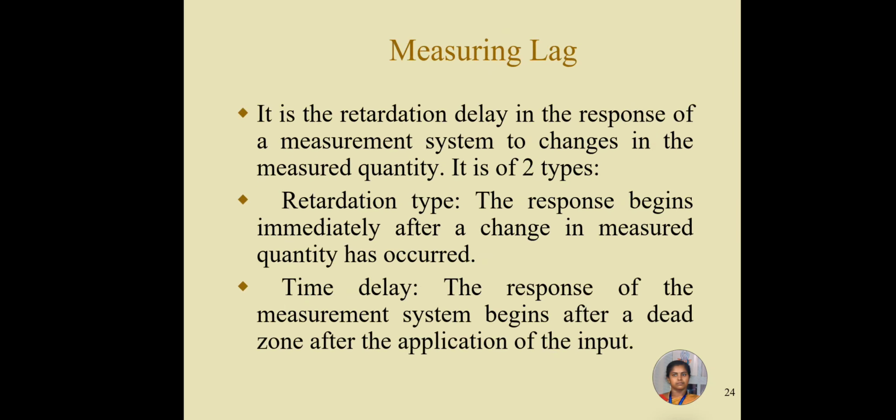The next important characteristic is measuring lag. That is nothing but the retardation or delay in the response of a measurement system to changes in the measured quantity. It is of two types. One is retardation type, another one is time delay.